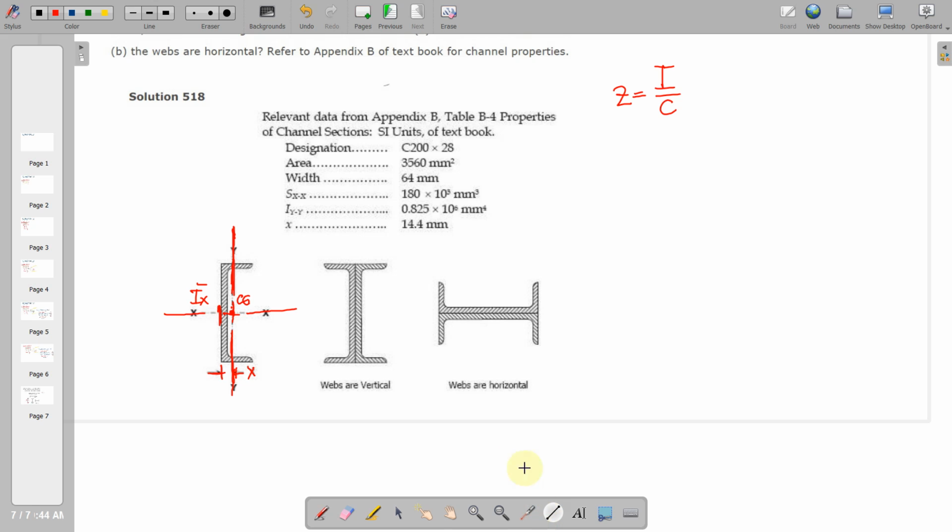So there's no problem if the flange section is where the webs are vertical. We'll just have to bisect this, and this will be our y because obviously the center of gravity lies within the center or the joining portion, since the channel is symmetric. Okay, and of course we'll just have to get the mid of this portion, and this will be our x.